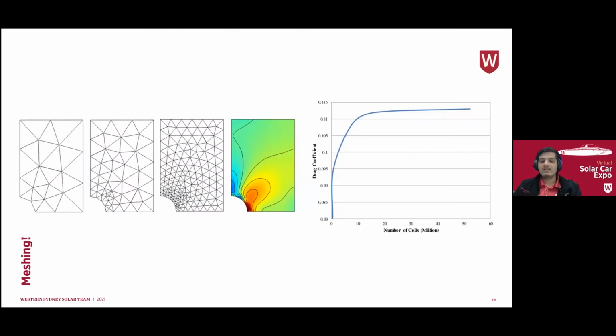Now, in both of these analysis types, one very common step was meshing. Both simulations are based on specific mathematical models. FEA, for example, would not provide you with any more information than just solving a free-body diagram if it applied the mathematical model over the entire component, considering it as a single item. However, if that component gets split into thousands of smaller cells that create a mesh of the part, the equations can be applied to each cell individually.